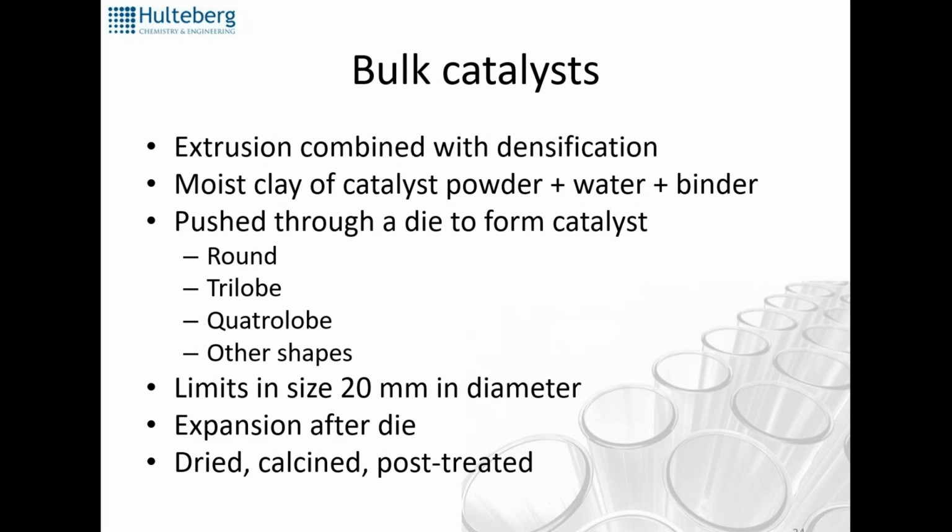It is also possible basically to do any other shape that you want, but the limit is roughly 20 millimeters in diameter. These clays that we create are rather thick, and you have to apply a really high pressure behind the die to push them through. That leads to a rather large expansion out of the die, so the die holes are significantly smaller than the final size of the extrudate.